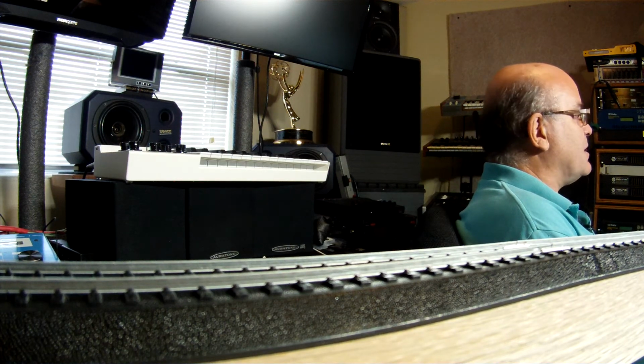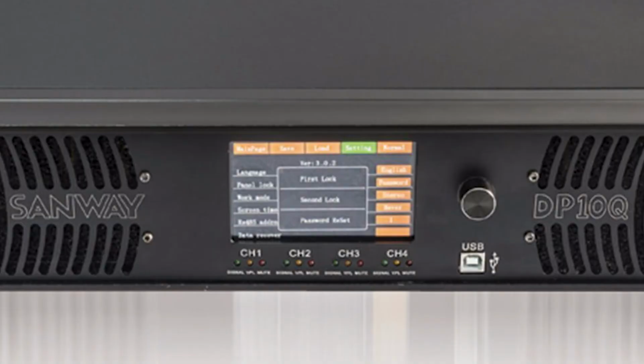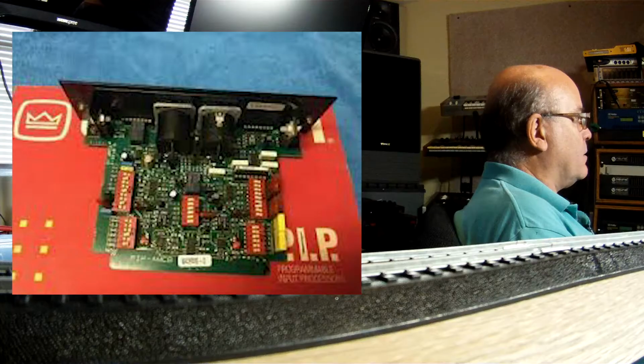In truth, in this day, many amplifiers, even inexpensive ones, have DSP, which means digital signal processing, built into them that eliminate the need for external crossovers, since all of this stuff can be done within the amplifier itself, along with a lot of other functions, including equalization, limiting, speaker protection. There's all kinds of stuff that can be done with that. Other amplifiers have modular input cards that allow you to select an electronic crossover ahead of time and similarly have it in the amplifier unit.